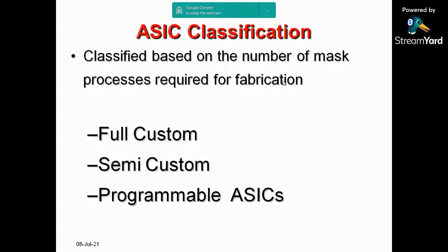Lithographic process is creating an image on the substrate. So suppose I want to create an N-type layer and a P-type layer, the SiO2 layer and everything. So I'll need a mask. A mask is, for example, a rectangular glass with a specific space where you can pass the UV light, right? So how will you create a mask? You need to draw layouts. I'll show you what the layout is. From the layout, you'll be getting the mask information.